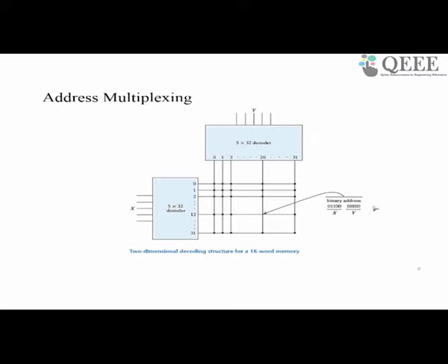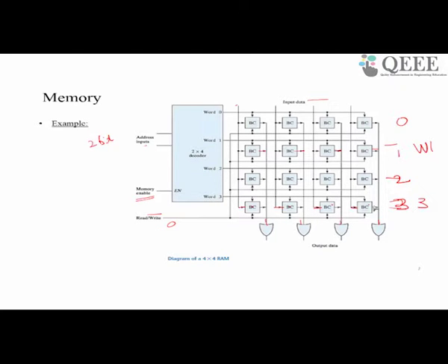Well, now let's look at this memory. It works perfectly well, but if you try to scale it up, let's see what problem arises. This is a very small memory, at least we want a little larger memory, let us say of size 1 kilobyte. Then each location has to store 8 bits. So 8 bit cells can be placed in each address location, but there have to be 1024 locations,